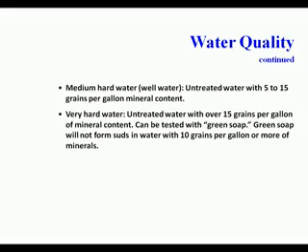Soft water is natural or untreated water, rainwater with a low mineral content, and has about 5 grains of hardness per gallon and no chlorides. Softened water is treated by an ion exchange process, a water softener, to remove hardness and minerals. Unwanted mineral ions are replaced with water-soluble sodium salts. Demineralized water is treated to remove the minerals.